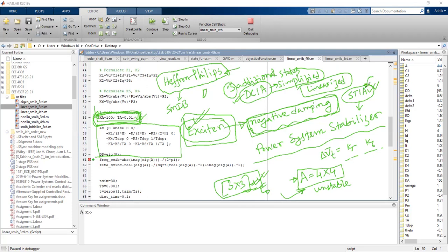This is one of the main reasons why we chose it as the exciter model to continue in our course, because we are interested in developing the Heffron-Phillips model, and that is possible with the simplified version of the IEEE ST1 exciter. After we start the Heffron-Phillips model, we will see how the incorporation of the exciter hampers the damping of the system, and then we will slowly move into the design of the power system stabilizer, inshallah.